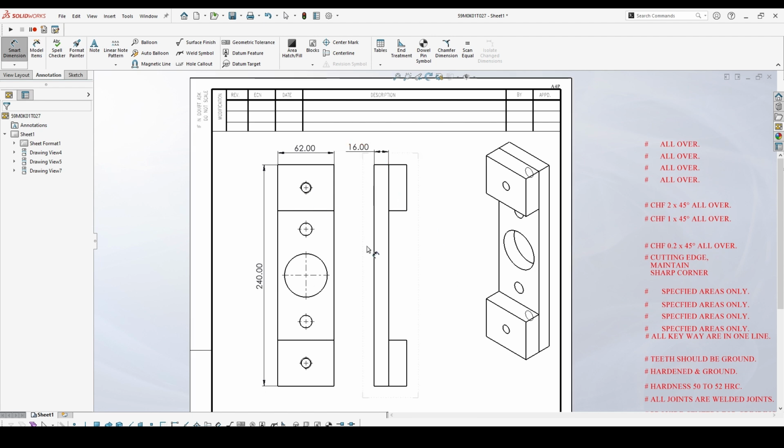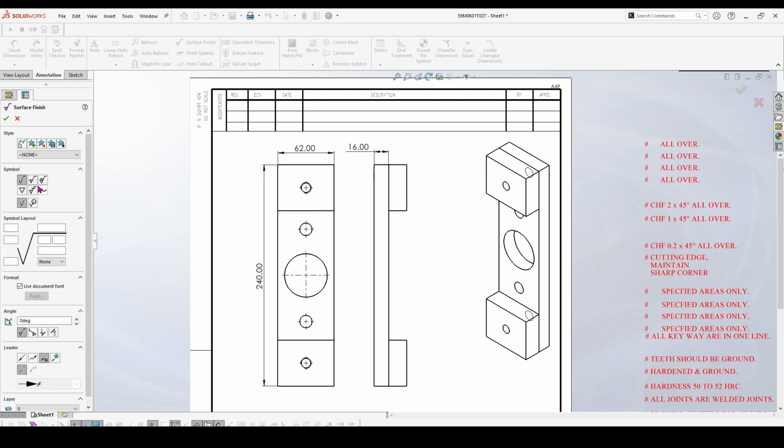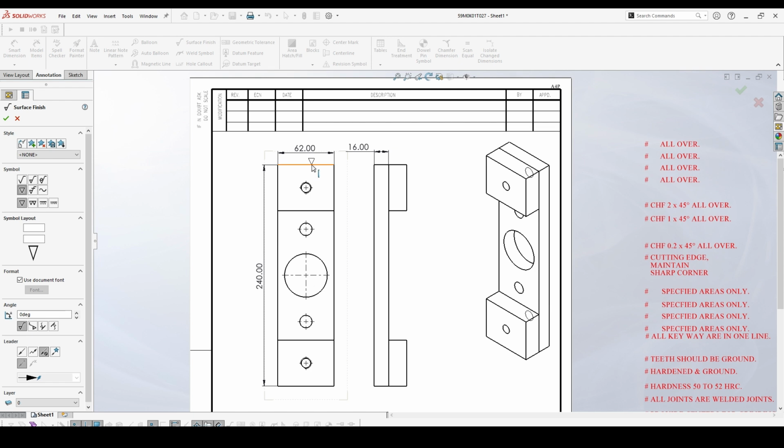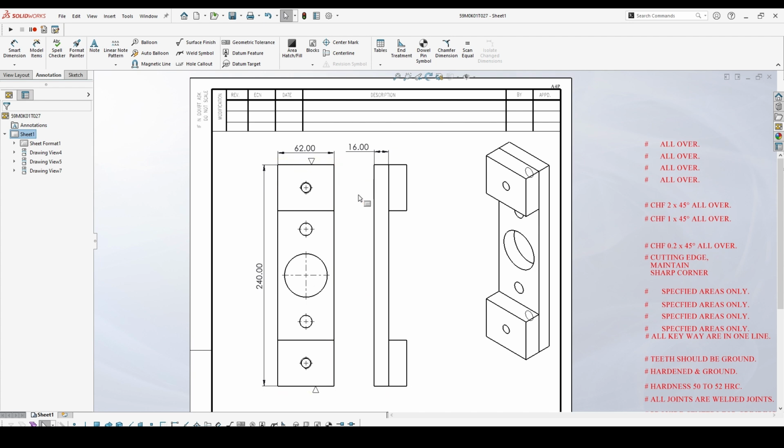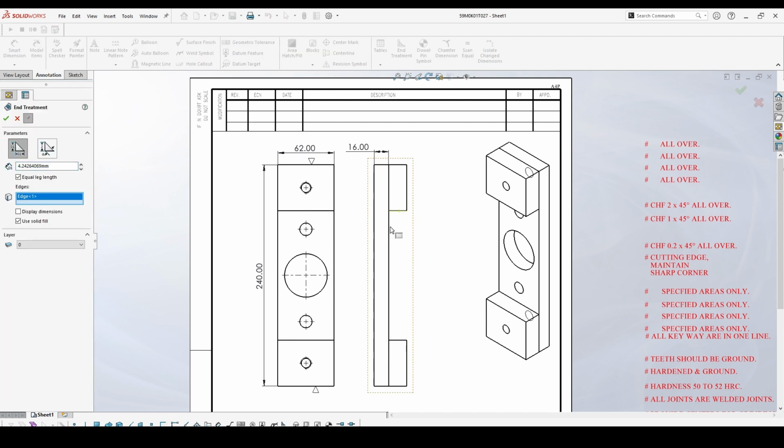This is a bright flat you can take as raw material. You will get a standard size of 62 by 16, right? And you cut 240 length. In this case you need a small machining symbol here, just to clean; we don't need it in this component application. So we have done the machining, and the length is completed. Then they have to cut these pieces to weld them. So we are planning to weld it like this. This welding size may go to 10 mm.